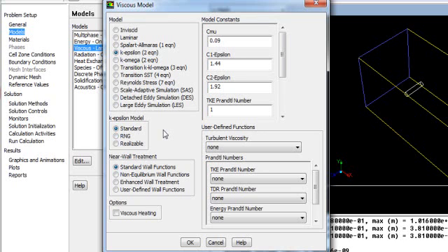You can find lots of literature based on turbulent model, especially K epsilon model, and for standard, RNG and realizable problem, you can study different flow phenomena and when we have to use realizable, when we have to use RNG. You can learn all of those things from literature or from CFD online. But for now, we are interested in how to set up the case for turbulent flow.